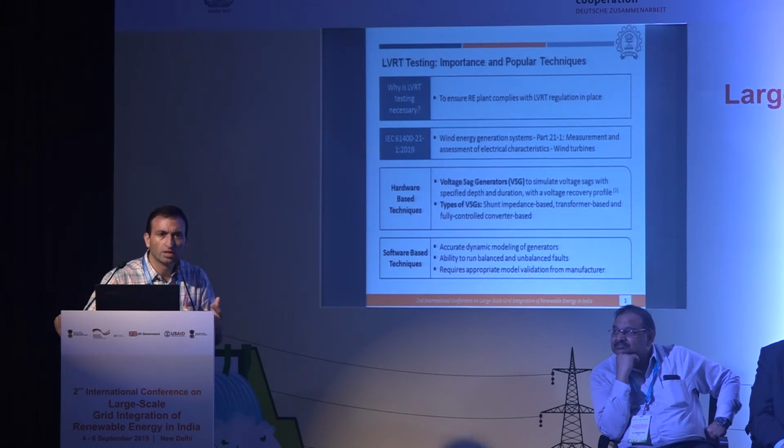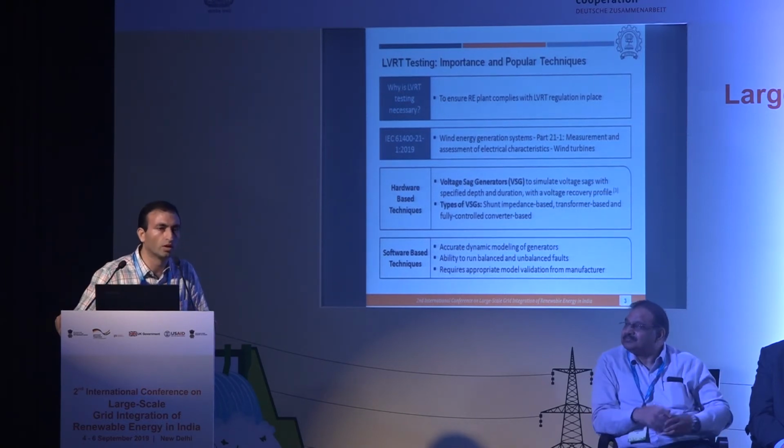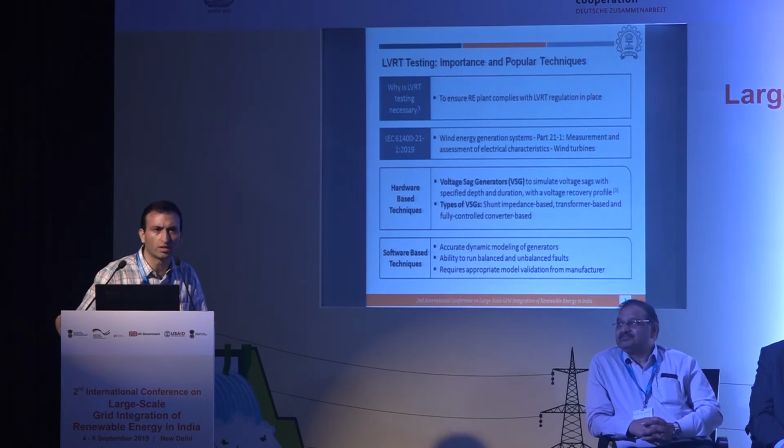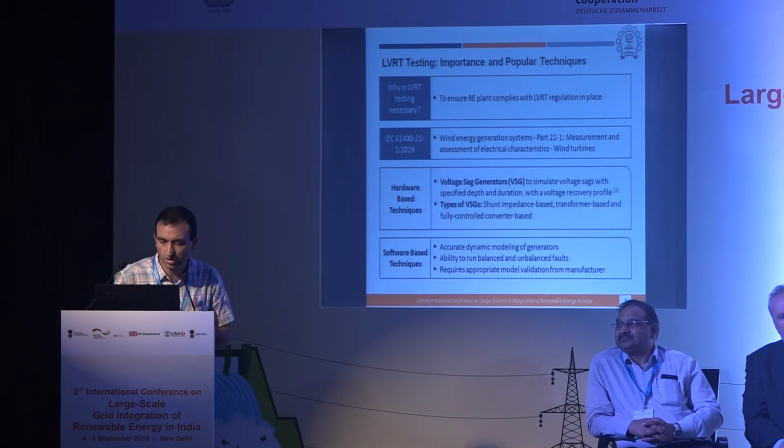So you have an option of self-certification where you give the validated model to MNRE through NEWA, and they check whether it complies with the grid code regulation of India or not. Accordingly, you get a self-certification which is valid for a certain period, I think around 1 year, and by that time the testing has to be done and shown accordingly.